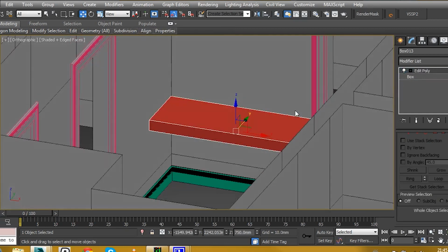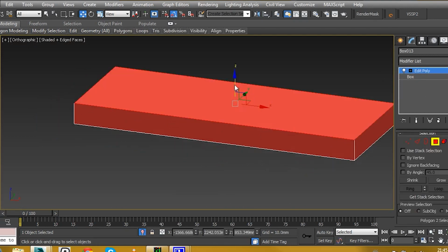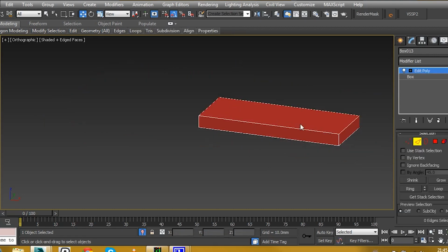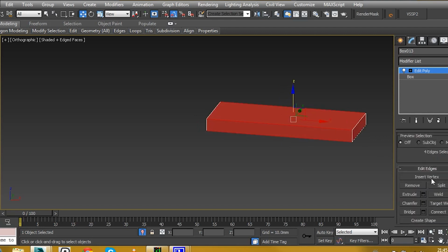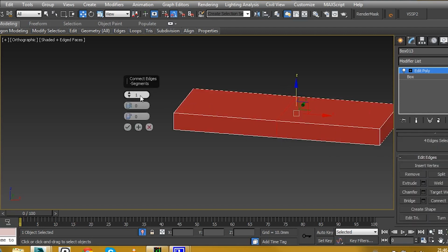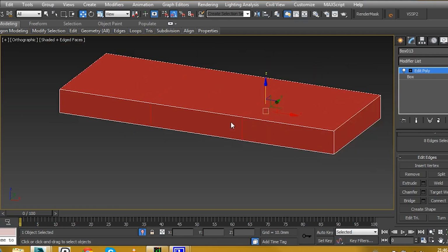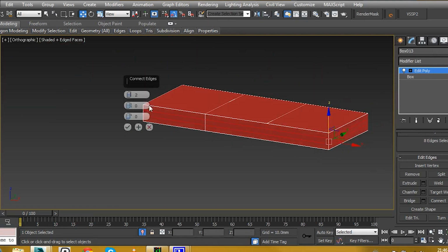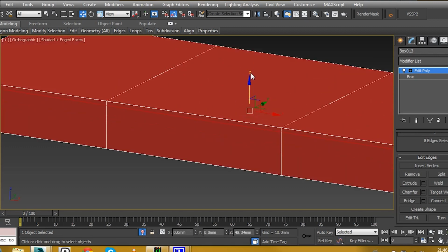So we just isolate our shape, and just going to give it a bit more height, about there. If you select your edge tool under edit poly, we'll select down the middle, and we'll go to connect. We'll just create two lines here, two segments, just there, and OK that. This is where the drawer will be. So if we bring these edges round here, go to connect and connect one segment, we'll just pull this up slightly, just about there.